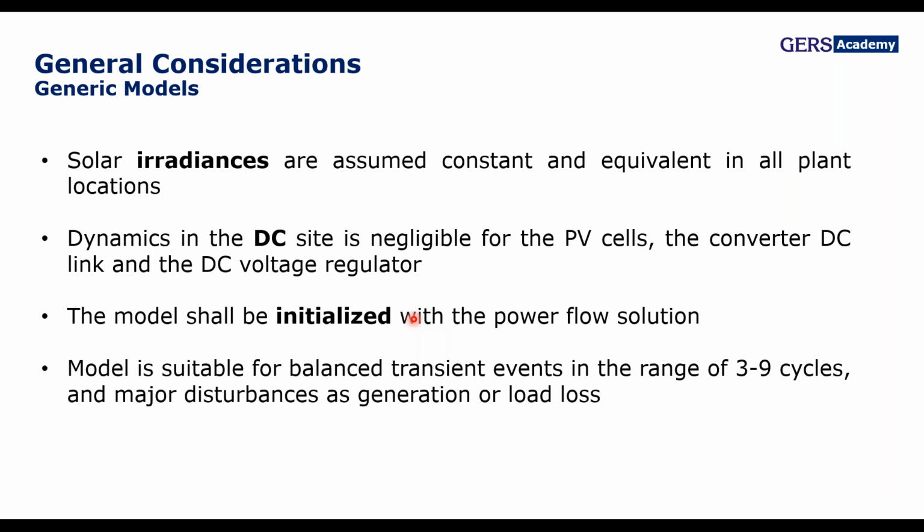However, you will see that there are some controllers that at least try to simulate a drop in active power. So what you expect is that under frequency changes, you will change the dispatch of generation. But that is a bit limited, since in the case that frequency just decreases, you cannot make the sun shine brighter.